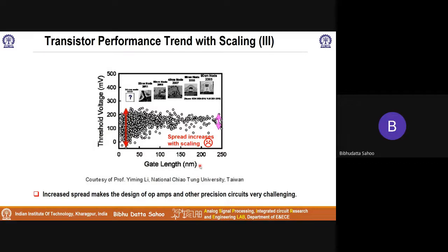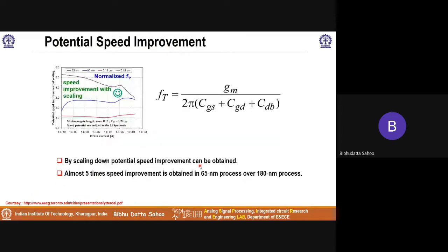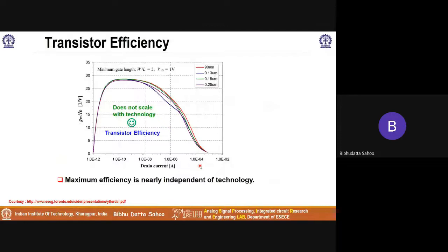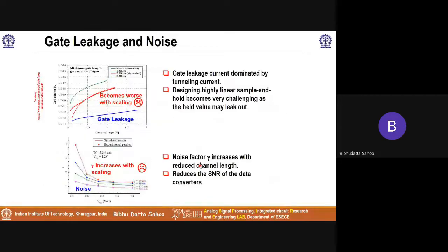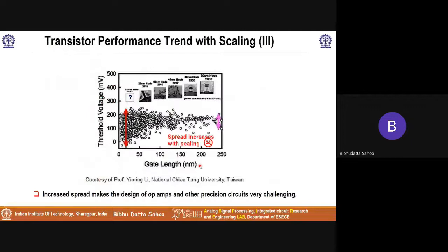I just want to reiterate that all these points translate to power consumption. So I hope that is clear. That's why I started off with the power consumption expression first in an analog circuit. But keep in mind the F in an analog circuit will be replaced with the bandwidth. It is not the switching frequency, because in an analog circuit there is hardly any switching. It is mostly analog signal swing. In a digital circuit there is switching happening.